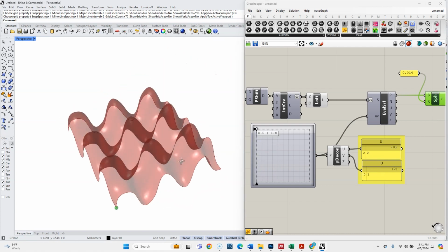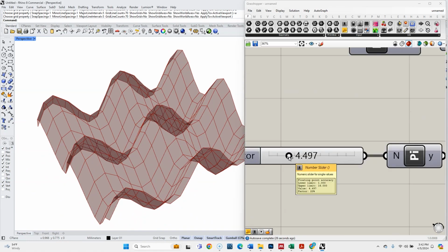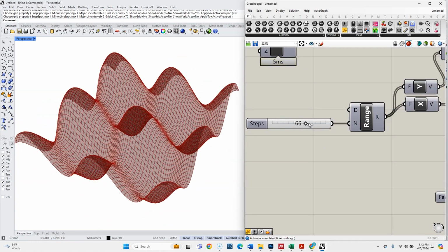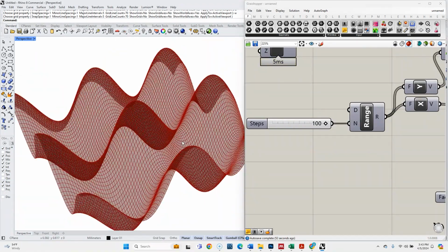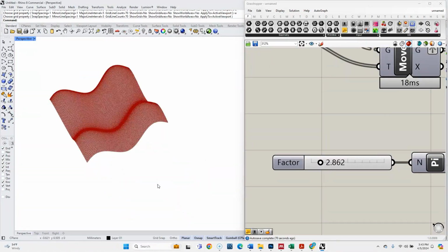And then we'll treat the u and v inputs as discrete inputs rather than the continuous nature that the surface class provides, so that we can move from a continuous surface into the territory of meshes, discrete meshes. We can think of a mesh as a discrete version of a surface, just like a polyline is a discrete version of a curve. And computers really do prefer discrete over continuous. This is how they operate, in discrete steps.